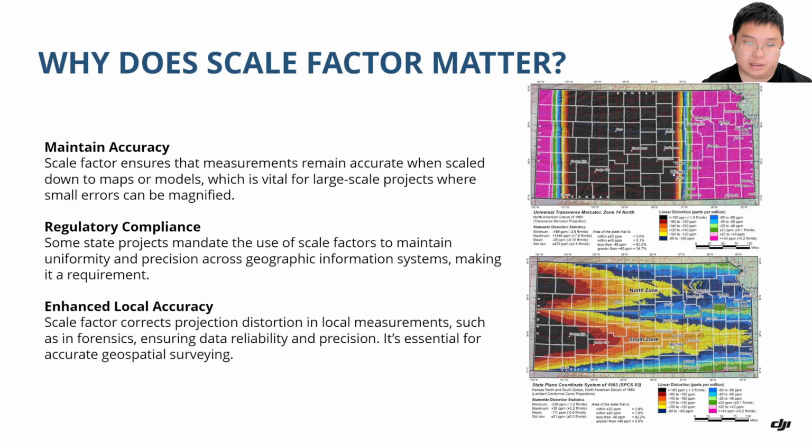Other states, on the other hand, may not require you to apply scale factor, but to ensure the accurate measurements on the ground surface, especially for those states at high elevation, you would probably want to apply scale factor, ensuring your output result is measured correctly.